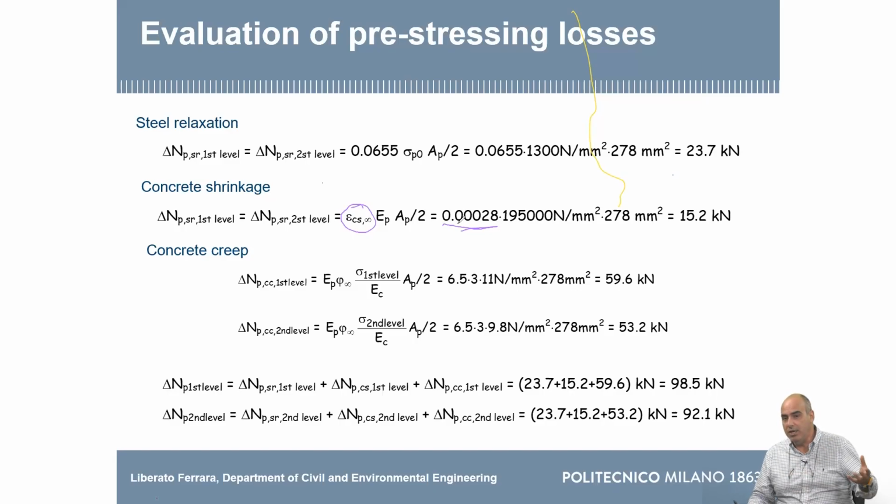What is thus change is that shrinkage is composed mainly of two parts. One is drying shrinkage, which depends on the hygral exchanges with the environment. The other one is autogenous shrinkage, which depends on the fact that if you sum up the volume of the reaction constituents, the reaction products are lower. So there is this autogenous shrinkage. In normal strength concrete, autogenous shrinkage is very, very low and is negligible, while in high strength concrete, it becomes more and more important.